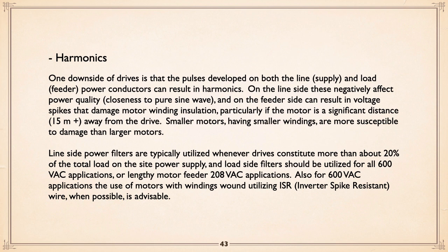Now you can use line filters, and anytime drives constitute more than about 20% of the load, certainly all pump stations, but even in a treatment plant, if drives are more than about 20% of the total load, then load side filters should be utilized for all 600 volt applications or lengthening motor feeds at 208. I say that because 600 volt or 480 is more susceptible to doing damage than the lower voltage. Like 208, normally you don't even bother with filters. So probably 240, same thing.